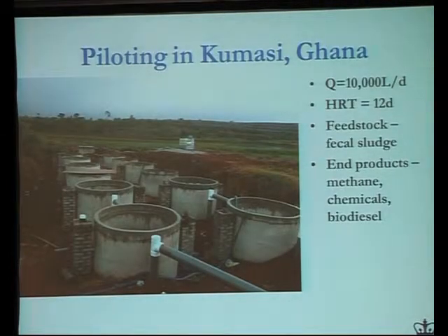And so this is really the heart of the system. It looks a lot more complete now, but the reason I wanted to show you this is because if you look at the design, it's basically a very conventional anaerobic fermentation digestion process. What we are doing is we have allowed ourselves the flexibility to tap into this process at multiple reactors down the chain. The last couple of reactors will of course produce methane, but we have the flexibility to tap into the chemicals which are precursors of methane, which are also precursors of biodiesel, by the way.